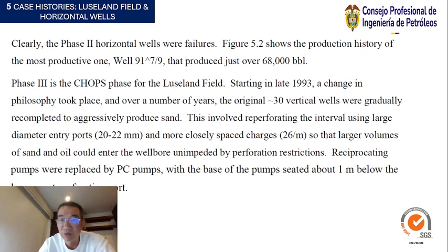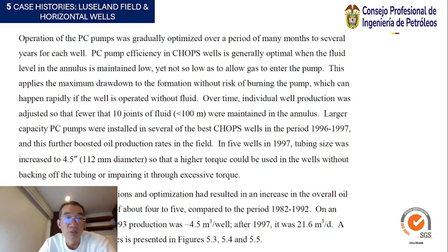unimpeded by perforation restrictions. Reciprocating pumps were replaced by PC pumps, with the base of the pumps seated about 1 meter below the lowermost perforation port. Operation of the PC pumps was gradually optimized over a period of many months to several years for each well.